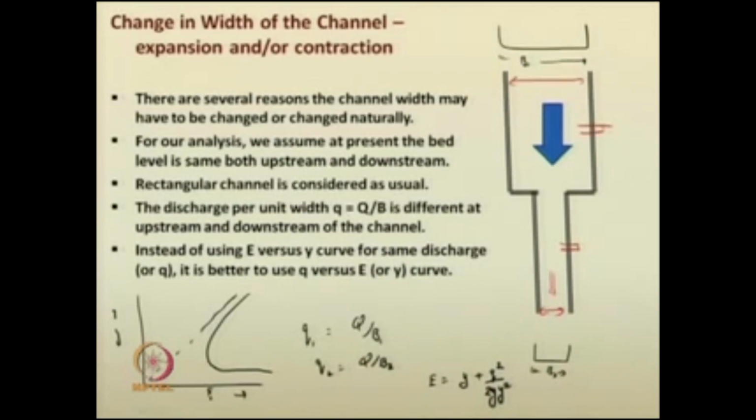Now, what happens if the width of the channel is getting changed? Definitely q is getting changed. So, the specific energy at the upstream location and the specific energy at the downstream location are now different. You cannot use the same specific energy curve, because the conditions are getting changed there, right. You have different specific energy criteria at the upstream and downstream locations. So, how will you analyze them?